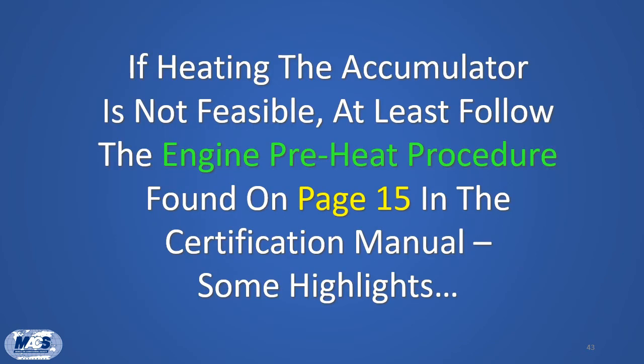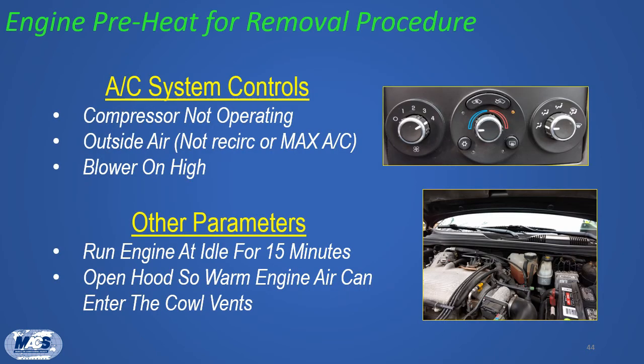But if you can't get to the accumulator, if heating it is not feasible, then at least follow the engine preheating procedure that's on page 15 in the certification manual. Let's take a look at that right now. It's called the engine preheat for removal procedure, and it assumes that you've already done one pull with your recovery machine to try to recover the refrigerant from the system.